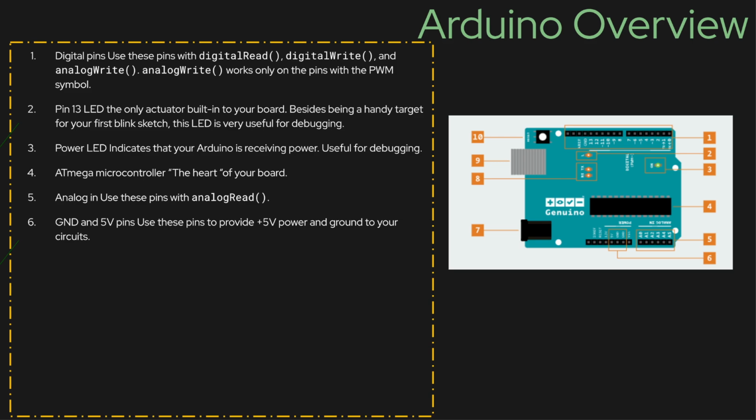But you can, and we're gonna be doing this in labs, actually wire up an external power supply, like the one that we were using in the labs before, to give more voltage. You can overpower an Arduino though, so you don't really want to do more than 12 volts from an external power source.